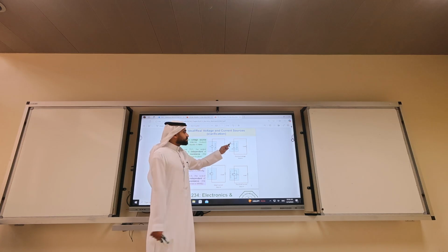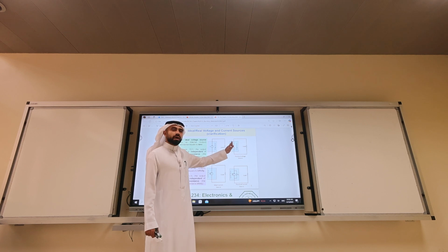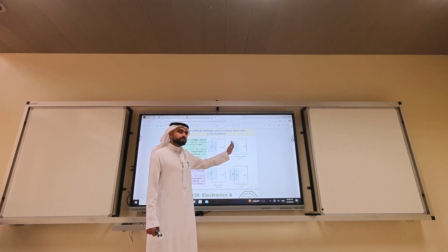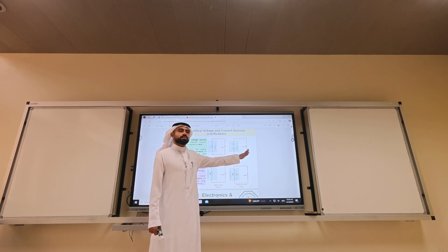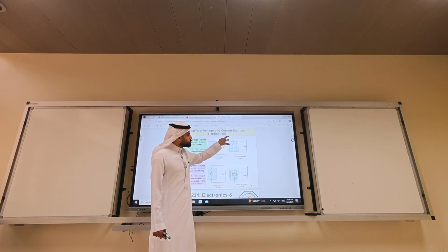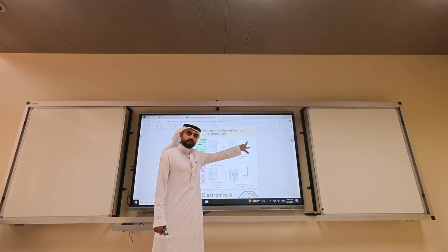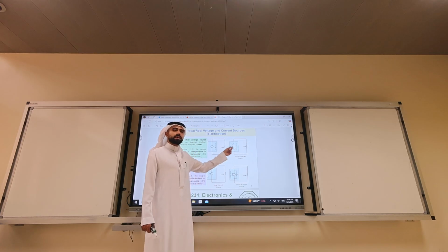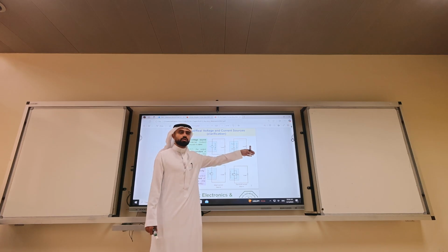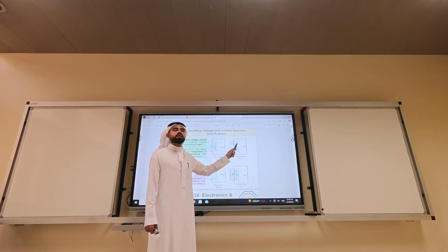That's why. The voltage source has an internal resistance of 5 ohms, and the load is 5 ohms. Using VDR, 5 volts will appear here, 5 volts will appear here, 50% here, 50% here. So we're wasting 50% of what could have been delivered to the load due to the high internal resistance.